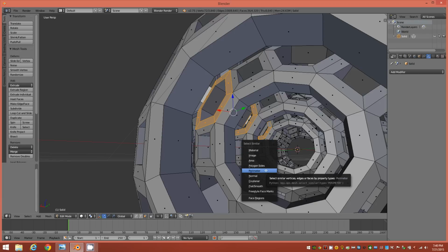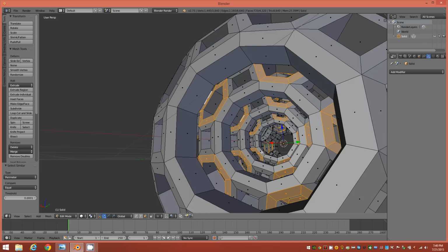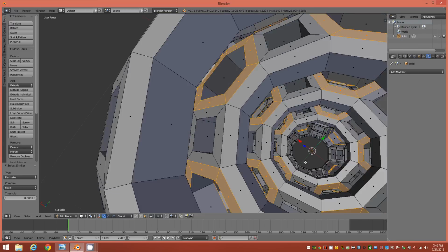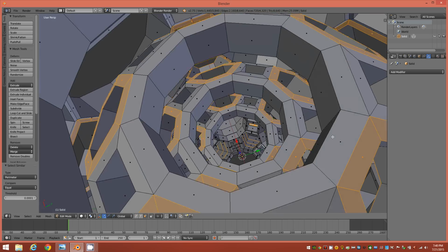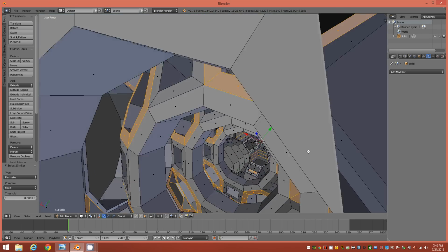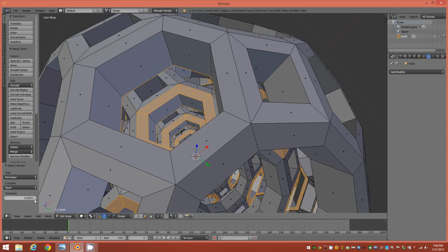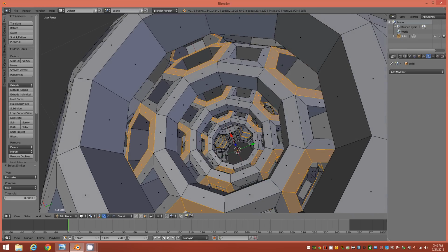and we'll choose Perimeter. Then over here in the parameters on the left hand side, we'll adjust the threshold to 0.0001 and hit enter. We'll examine our objects to be sure that we've captured all of the proper corresponding faces, and that it hasn't captured anything that we don't need. Depending on your scene scale, you may need to alter the threshold either more or less to get the proper face selections.